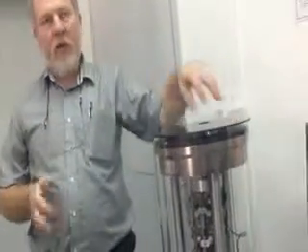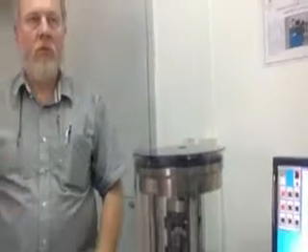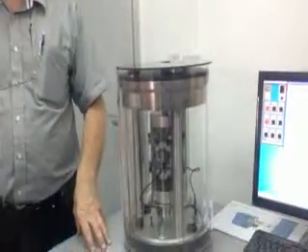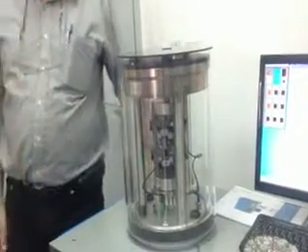The dynamic modulus test is not a failure test. The test itself is almost like elastic: you apply the frequencies and loads, and you release. So you are not going to load the sample till it fails. The sample will keep its shape. You are just trying different environmental conditions, different pulses and different temperatures. You apply the load and release it. It's not a failure.